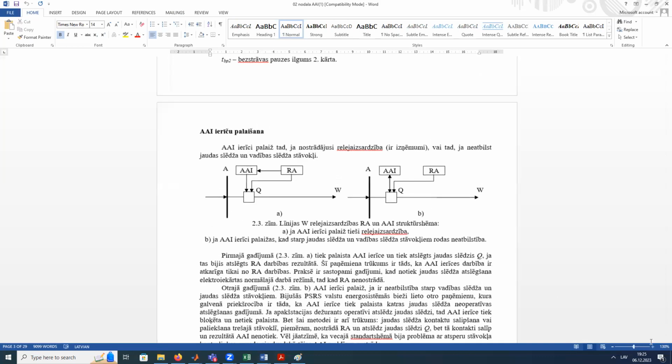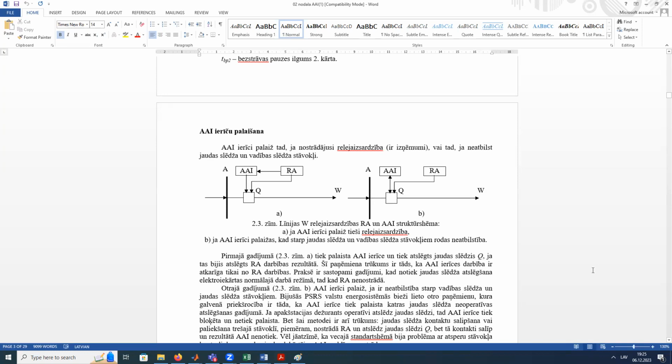Okay, first of all, what is a reclosing automation? What is the idea of reclosing automation? It's very simple. If we have a fault in a line, this fault could be temporary. For example, due to strong wind, a tree or a branch of a tree just connected the wires. And in several seconds or milliseconds, this branch, for example, burned up and was destroyed. Or, for example, due to this wind, the branch just touched a wire for a millisecond, and that is all.